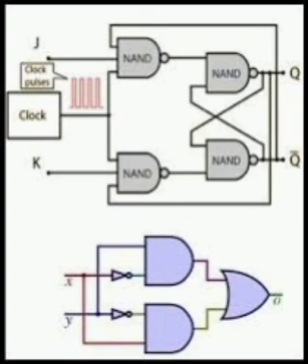Sequential circuits. Flip-flop is a basic memory element. It can store one bit of information. A flip-flop has two outputs which are always complementary to each other. A flip-flop has two stable states, hence it is known as bistable multivibrator. The simplest form of flip-flop is called latch. It can be constructed with two cross-coupled NAND gates or NOR gates.